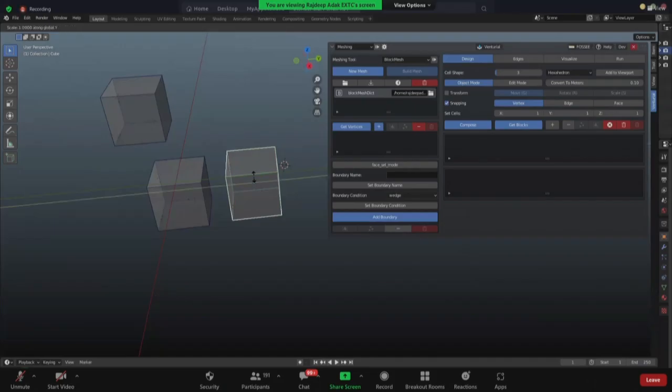What this does is it allows it to expand only along the Y direction. And I can move my mouse and move it around the Y direction. After pressing Y, I can press the button 2 to scale it twice its length along the y-axis. And then I'm just going to press enter. After that, again the G button, and I can move it as I require.